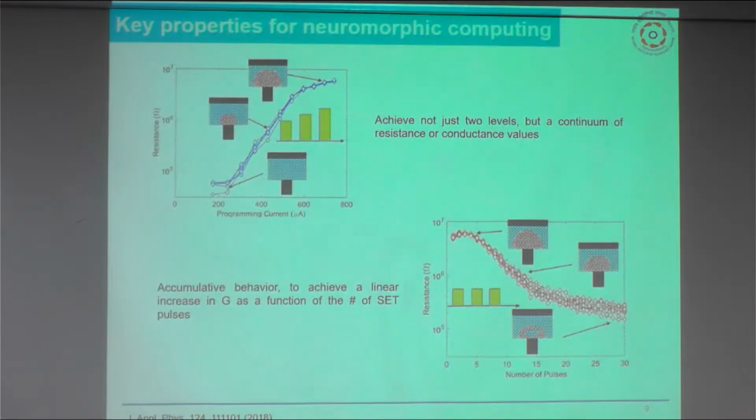That's why when we talk about neuromorphic computing, you just convert resistance into conductance level, and then you can identify the weight. This works for all memory technologies. You can see that in resistive memory, memristor-based, and some ferroelectric devices. They talk about the conductance weight and then identify it. Here, what they are doing is providing a number of pulses, and these are set pulses.